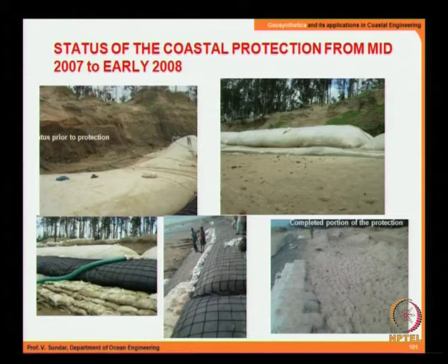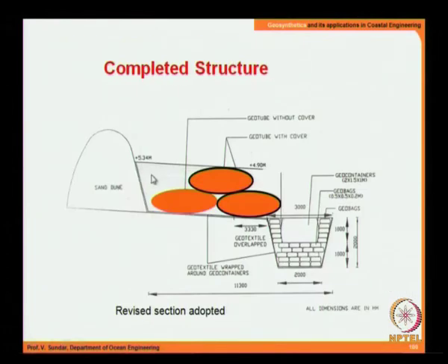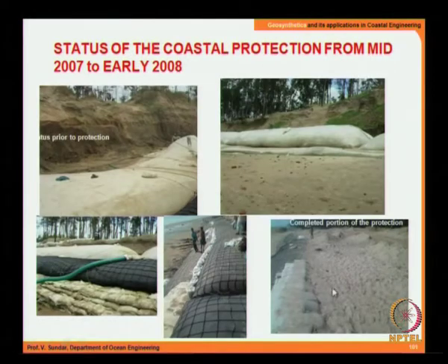So you look at the initial geobag, the bottom one, and then over which you see this bag. This geobag is provided with that UV stabilizer, and then once this was laid, you see the filling up of the position, that is this location was filled up with the beach material, so that the people are not starved.